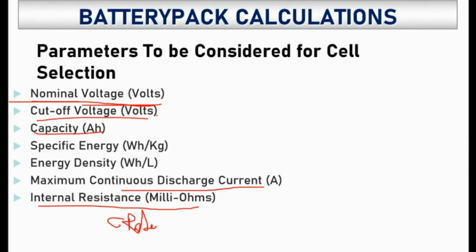The cutoff voltage is there to protect the system from under voltage. When you have a motor controller rated to operate between certain voltages, and you reach this cutoff voltage, your battery should stop providing power to protect the other systems present, like your DC and so on. This is why we have the cutoff voltage on the lower limit and the upper limit, and capacity.